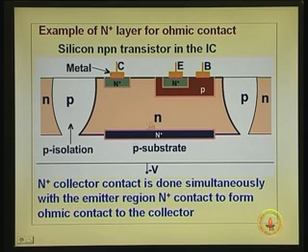Start with a p type substrate, and on the p type substrate you form this n plus layer in this portion, which is called a buried layer. Okay. The purpose of that is to dope the next n layer very heavily there. So, put an n plus buried layer there, which means you are providing a low resistance path for electrons.